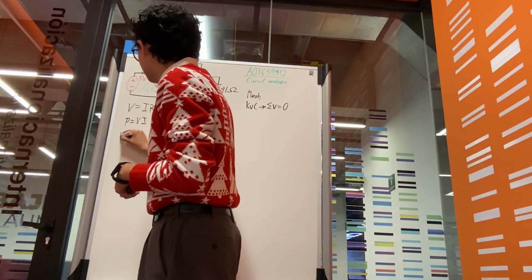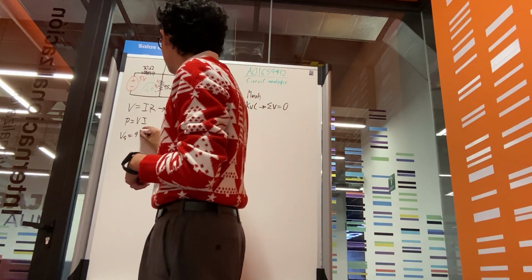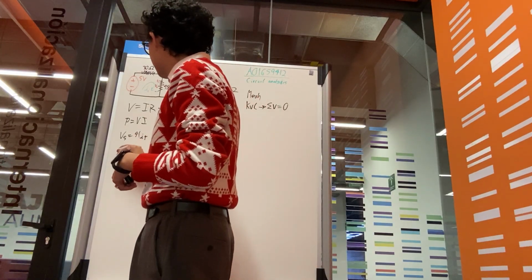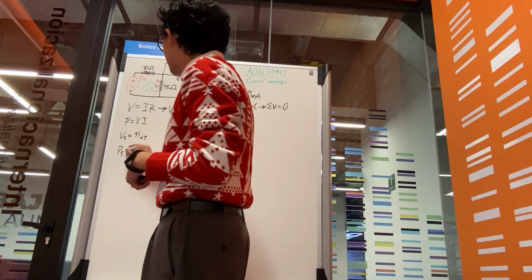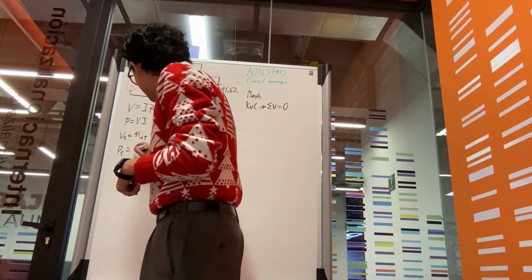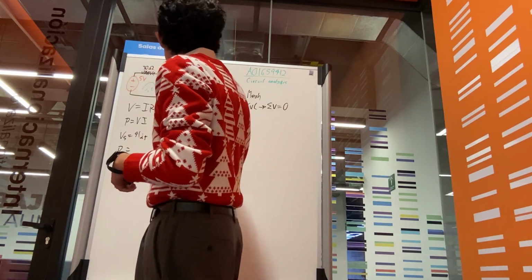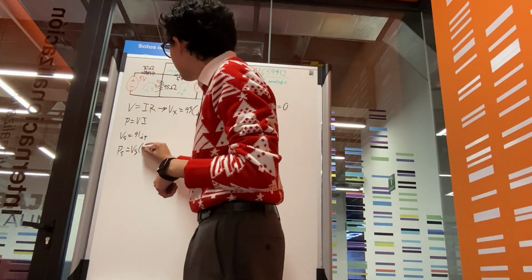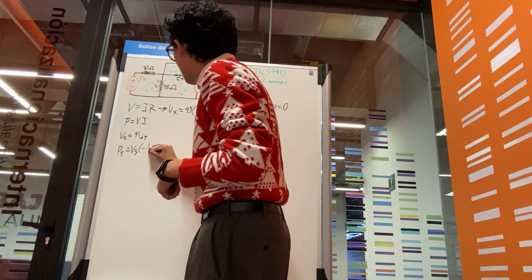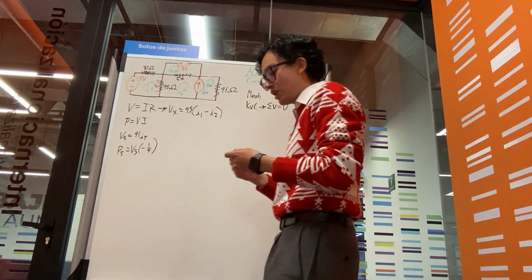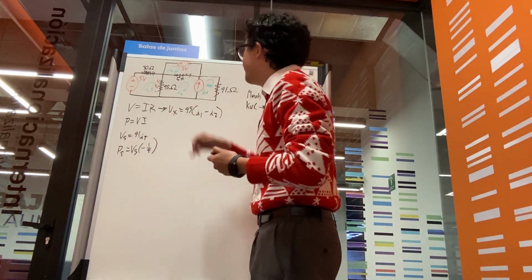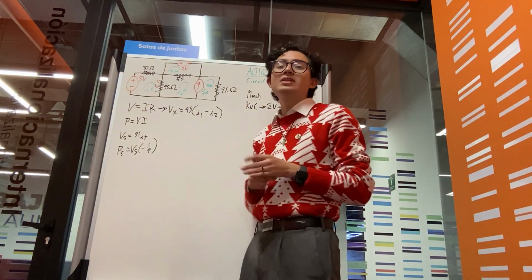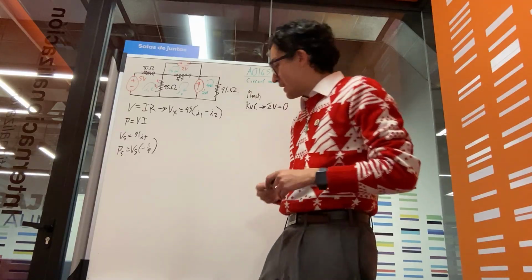So we first have to get the voltage source, in this case 41, times current 4, and with this we can get the power of the current source, which would be the voltage source times minus 1/4. It is minus because we're dealing with an active component, which means that this component is delivering power.